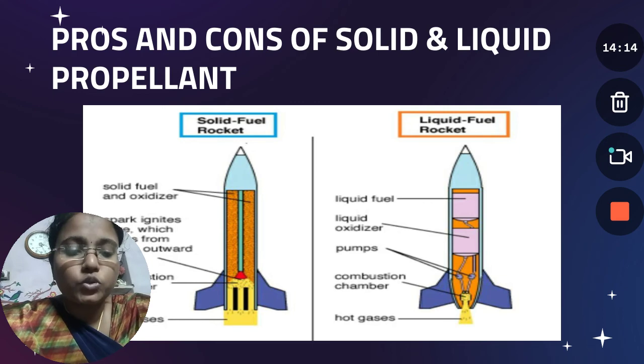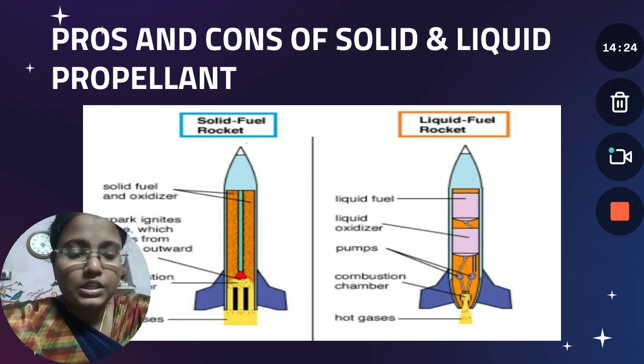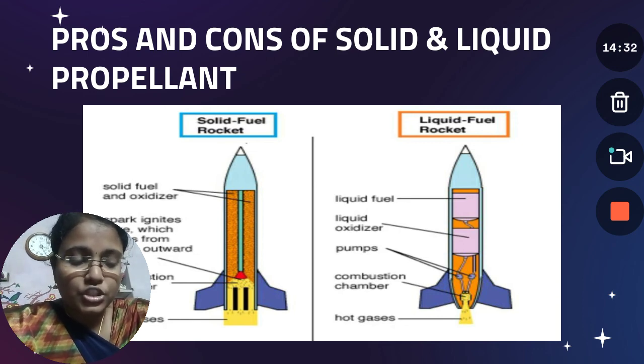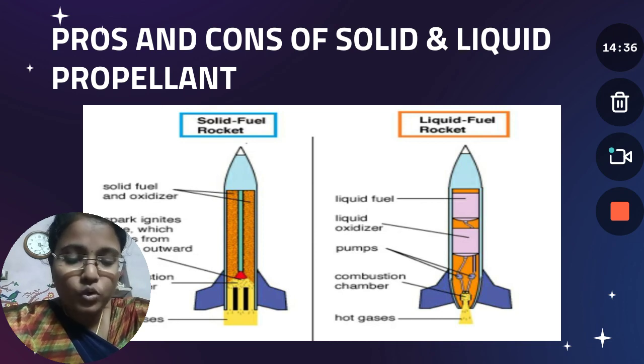Recovering a liquid fuel engine may be as simple as landing it using thrust, which is impossible with the solid fuel engine, which has to be recovered by parachute and usually landed in water to prevent it from crushing. Exposure to seawater increases the amount of refurbishment needed.